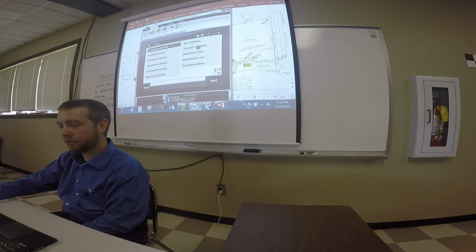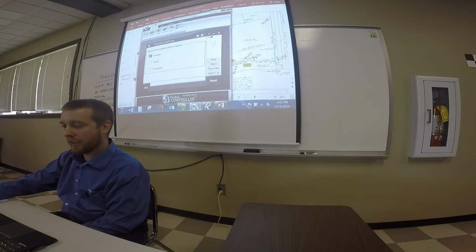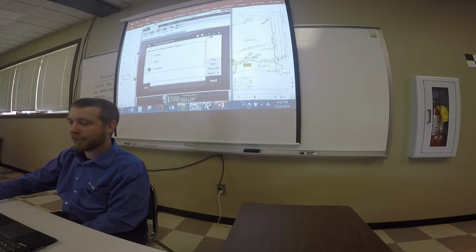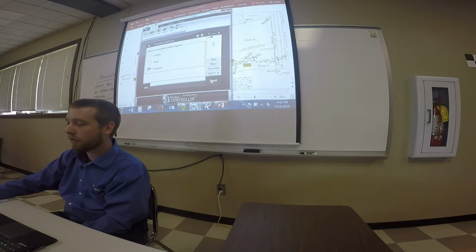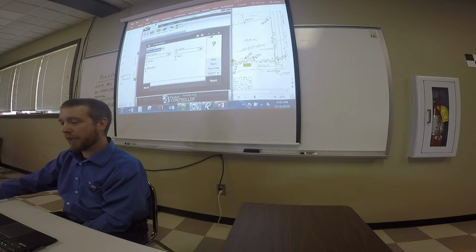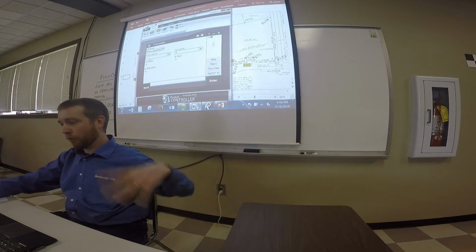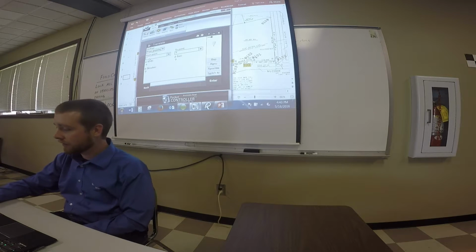Okay, so we'll go to transformations. Go to Cogo, transformations. And then what we want to do is translate right now. We just want to take that block of points and move them. So our method is 2 points. Our from is going to be our keyed in points down there in the middle of nowhere.